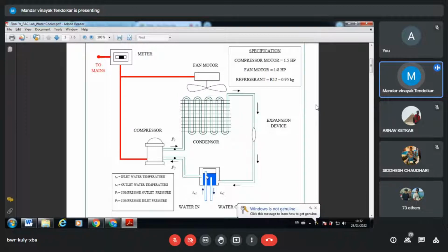Do you agree? Let me give you an example, a random value. Let's say -5 degrees Celsius. From the ASHRAE chart table, whatever I shared with you earlier on the GVC, whatever it is, -10 degrees, you will find the liquid enthalpy and vapor enthalpy. That will give me HFG. Correct? Of course this only involves the phase change part. If there is anything beyond that, like superheated and subcooled, that is the extra part.